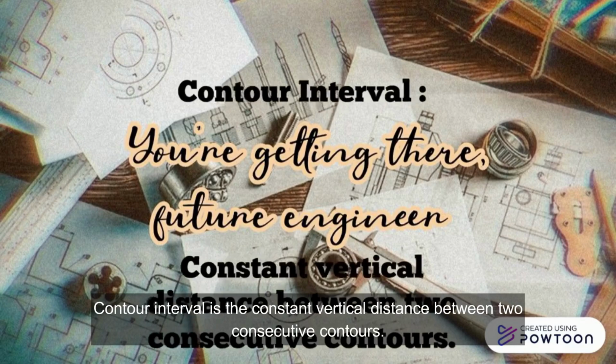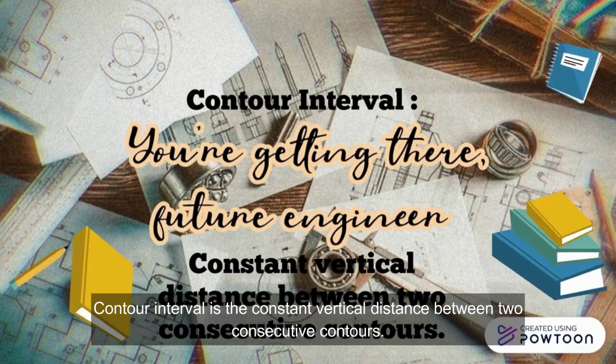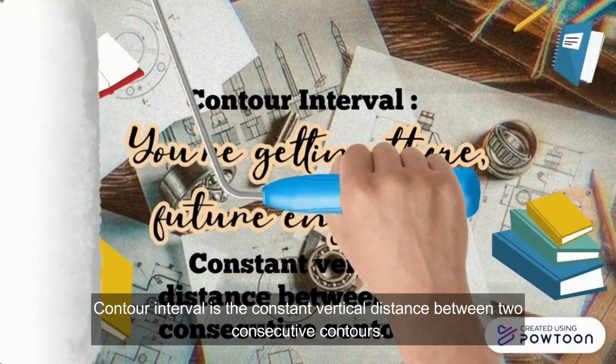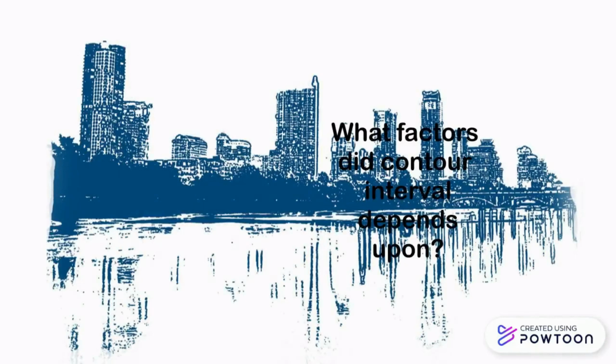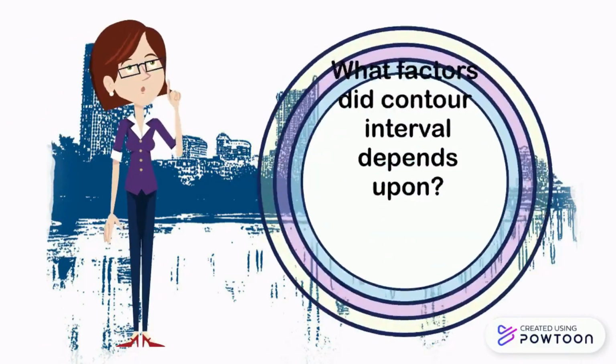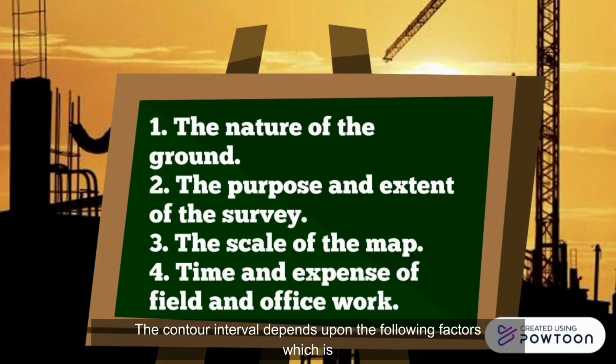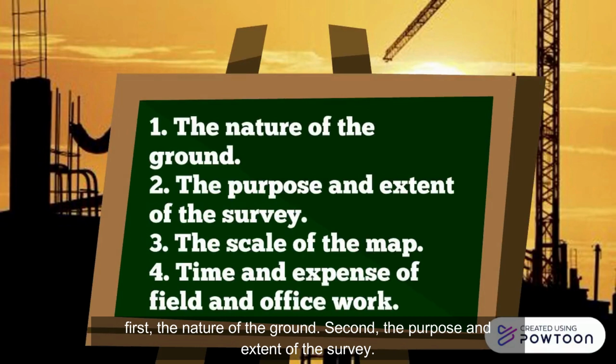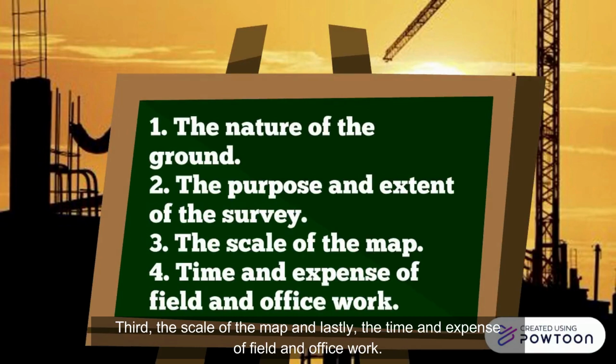Contour interval is the constant vertical distance between two consecutive contours. Do you ever wonder what factors the contour interval depends upon? The contour interval depends upon the following factors: first, the nature of the ground; second, the purpose and extent of the survey; third, the scale of the map; and lastly, the time and expense of field and office work.